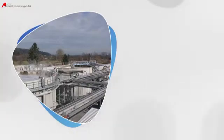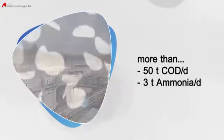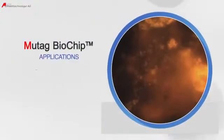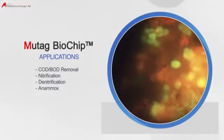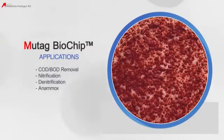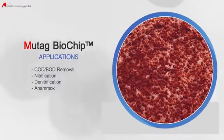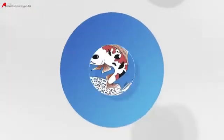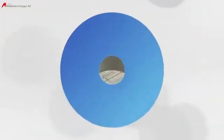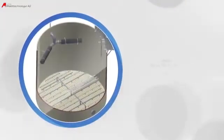There are MBBR plants which are treating more than 50 tons of COD per day, or more than 3 tons of ammonia per day. The Mutag biochip is used for water and wastewater treatment in general for COD or BOD removal, nitrification, denitrification, and also for NOx application. It is also used in many aquaculture applications for denitrification and nitrification too. It can be used in MBBR-based plants or in combination with activated sludge as an IFAS system.